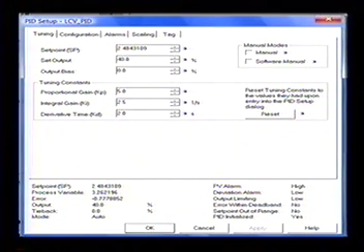So if you were careful at that point, you could actually open your output valve manually a little bit more, or close it a little bit more, and find that magic number where it's completely stable without any disturbances, right? At that point in time, you could actually see some stability. If you know that happens, then you know you've got a stable situation. And then what you would do